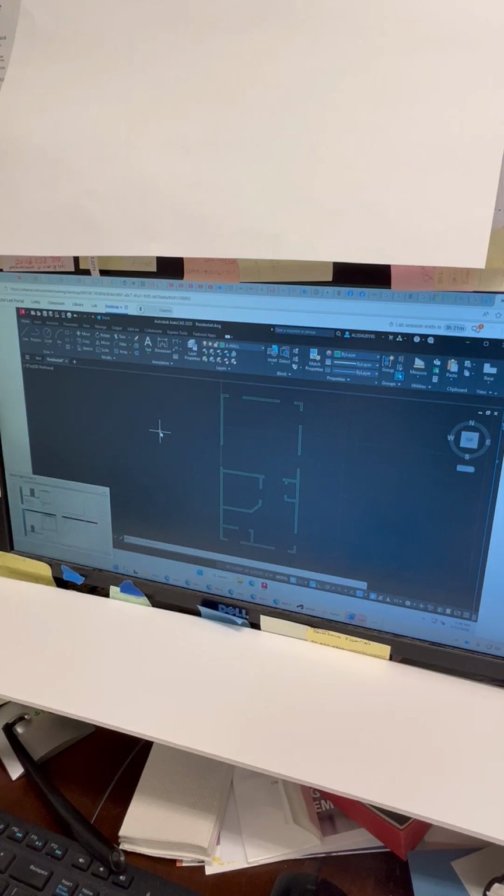All right, let's start with the window drawing, and we're going to bring it into our drawing, and it's going to be turned into a block. Now, here's the benefit of a block. Imagine this. Just watch me here, if I needed to show a window, and every time I start a project or a drawing, I have to come over here and draw a window.